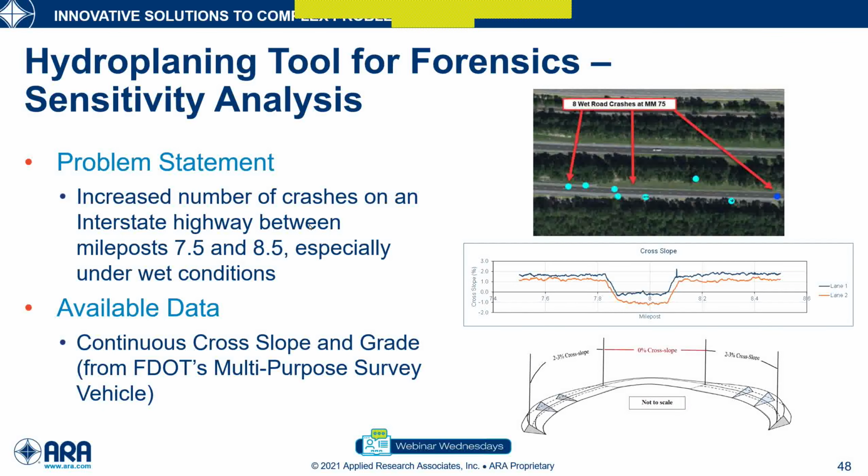And the sensitivity analysis has also been used under the forensic analysis. Here's another real-world example. This is another section of the interstate where we saw an increased number of crashes, this time between the milepost 7.5 and 8.5. And we sent our multi-purpose survey vehicle to collect continuous data, and I tried to do a 3D representation of what the crosslope looks like.